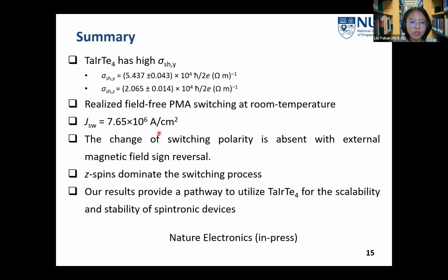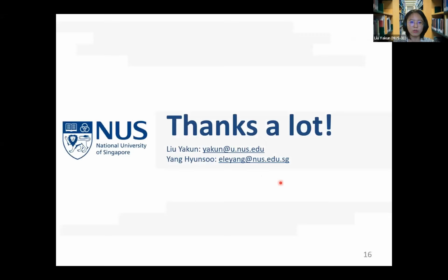Most importantly, we also note that the change of switching polarity is absent with external magnetic field sign reversal. Meanwhile, we know from our simulation that the Z-spin dominates the switching process. So our results provide a pathway to utilize TaIrTe4 for the scalability and stability of spintronic devices. The above work has been accepted in Nature Electronics and is now in press. So that's all. Thank you.